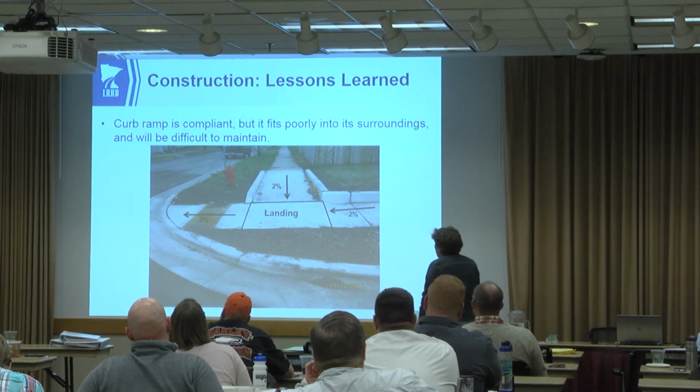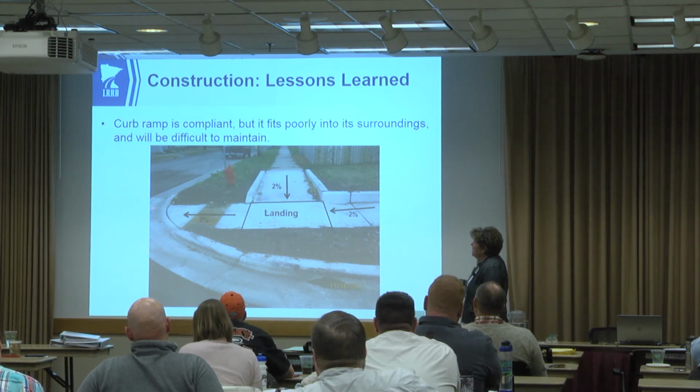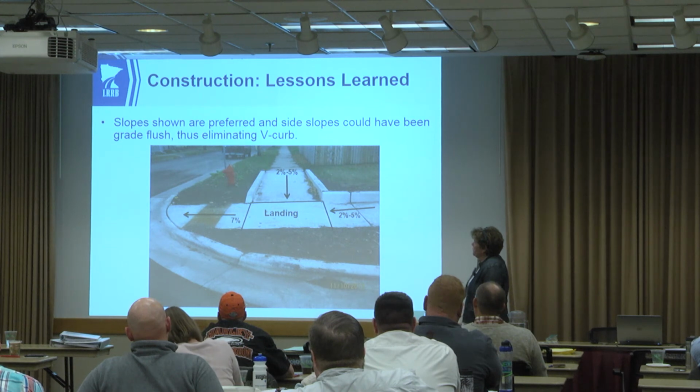Another example here, we see a bunch of flat slopes, but we have this vertical curb. If we were to lift this landing and put in some steeper slopes here, we might be able to eliminate the vertical curb.